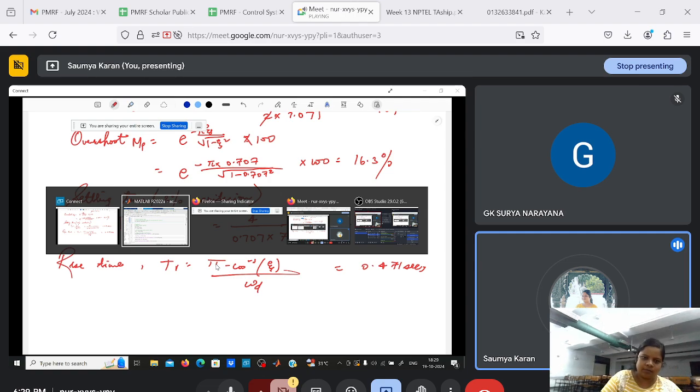Now let's see how MATLAB does this. So your numerator is 50, and 1 10 50 is the denominator. Transfer function numerator denominator gives you the closed loop transfer function. This stepinfo of G gives you the performance specifications corresponding to the step response. Then we print rise time in 3 float format, MATLAB 3 places after decimal, settling time, and we print the overshoot. So info.Overshoot, info.SettlingTime, info.RiseTime help us in accessing all of these. Then we plot all of them with grid.